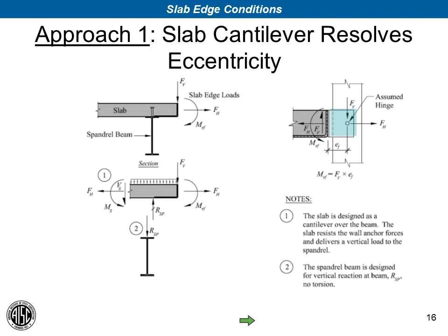So let's walk through this figure. Starting from the right, we've got a facade attachment. In this case, it's graphically shown as curtain wall, but it could be any number of different options. The facade system applies a vertical load and a horizontal load directly to the slab edge, and the slab edge transmits those loads to the base building structure. In this case, as a beam acting in flexure, applying a reaction to the spandrel beam, as you see here, and dragging horizontal loads into the floor diaphragm.